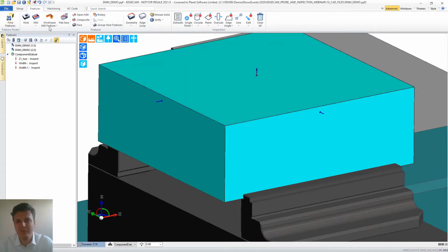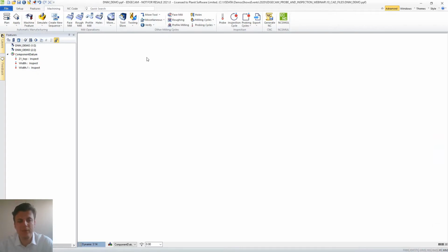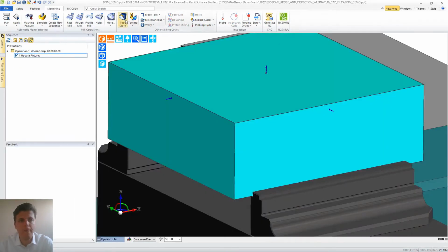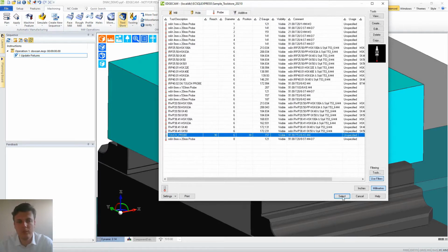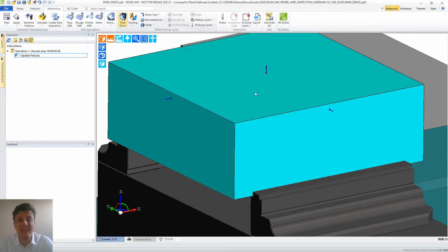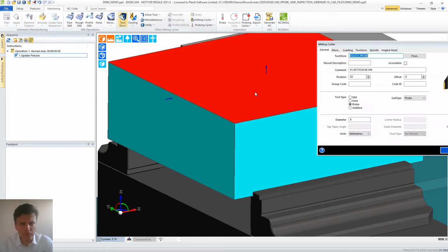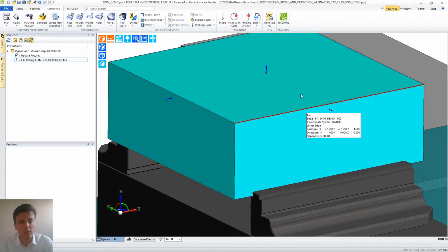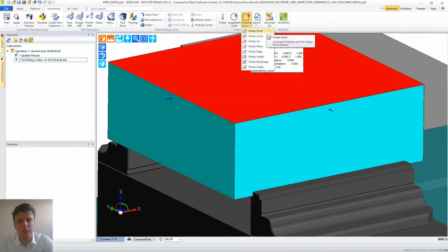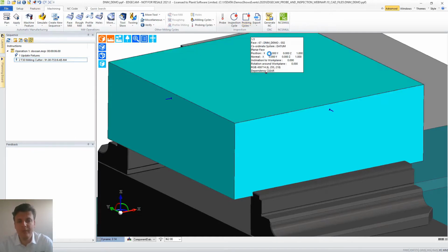Alright, so after that, once you have the feature, you just have to select them as a stock. But let's select first a touch probe. Yeah, so touch underscore probe. This is the name of the probe on the machine. Remember, it's a Siemens, so I have to call T=, the tool code, and then touch probe. So these are the new cycles: point, circle, plane.